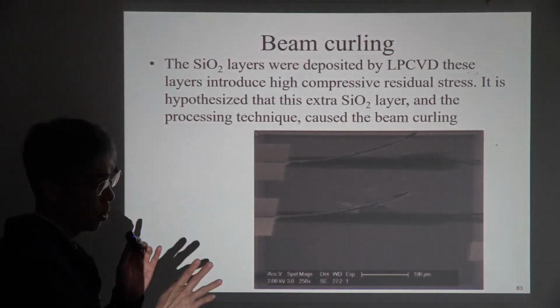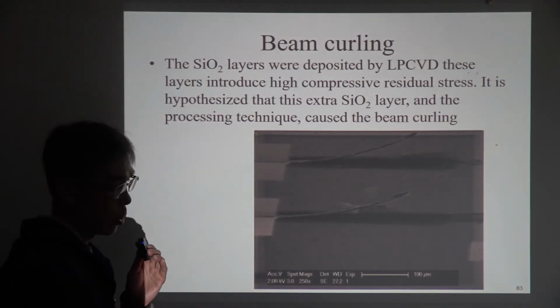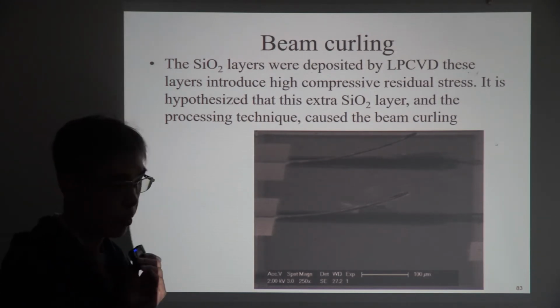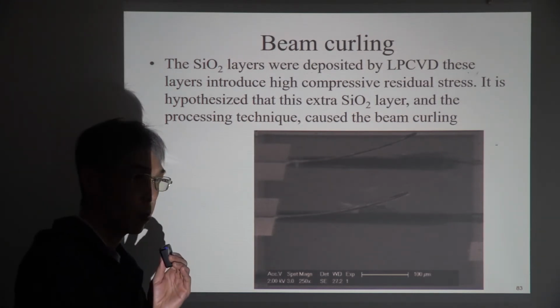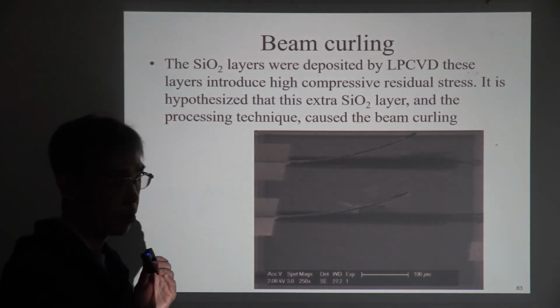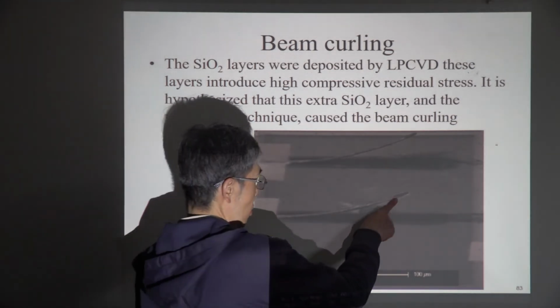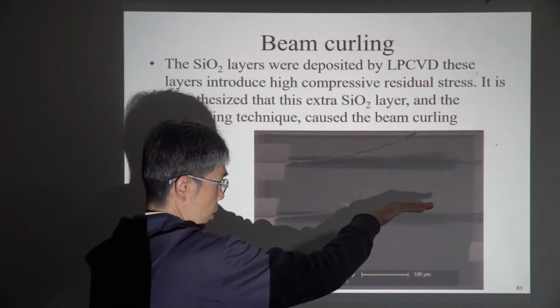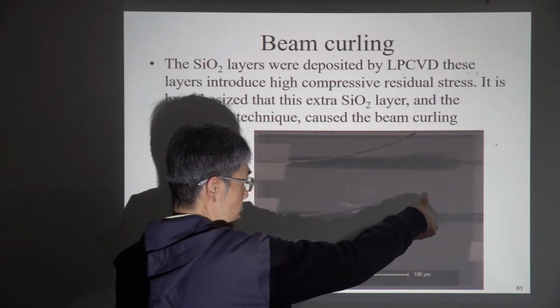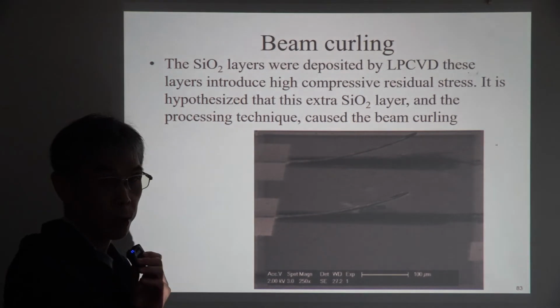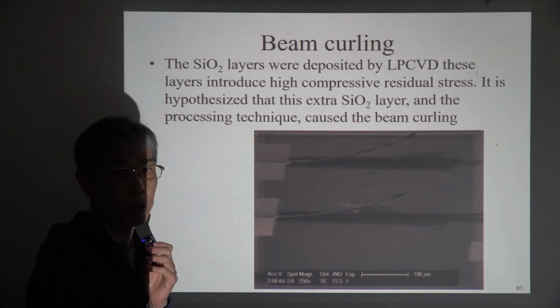But in the real world, we need to have force equilibrium and moment equilibrium. So in order to reach the force equilibrium and moment equilibrium, the beam needs to generate a bending moment this way. If we have a bending moment this way, it means we are going to have tension stress near the upper part of the beam.